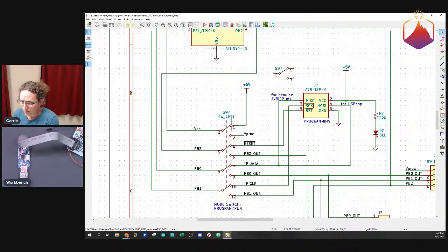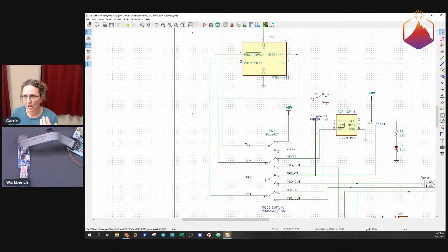So the reason for doing this is a few things. You basically have to use these pins multi-purposefully because there are so few pins. On a processor with more pins, it's generally good procedure, if you don't need them, to use the pins that go to your programmer exclusively for programming, and not hook up anything else to them, because other external circuitry might affect the way that it programs.